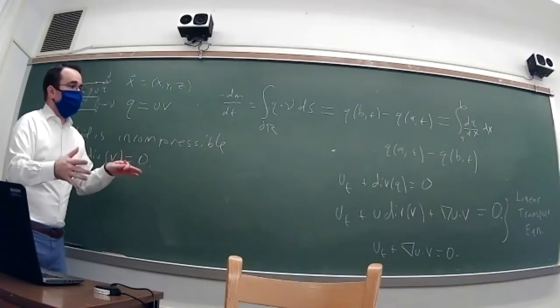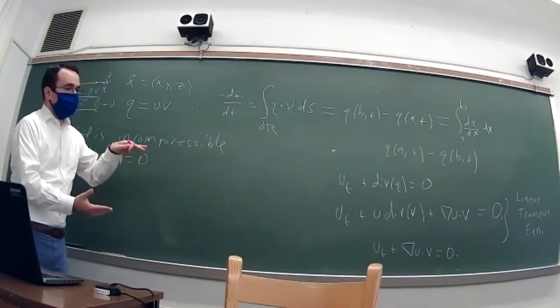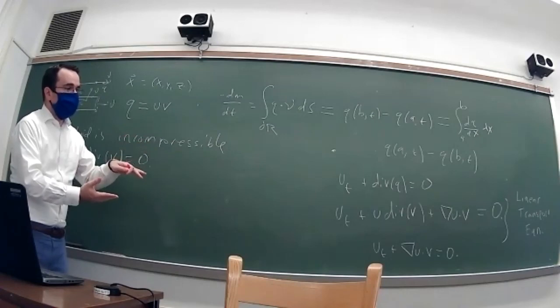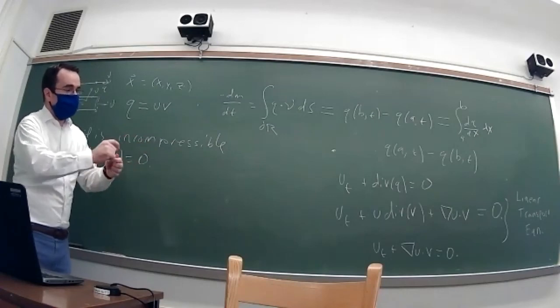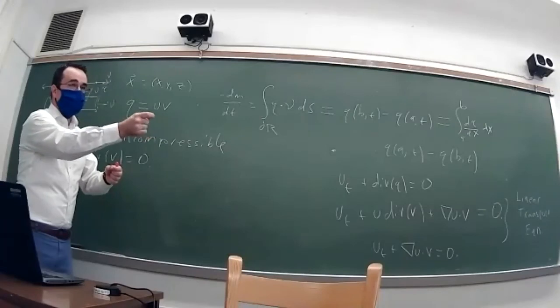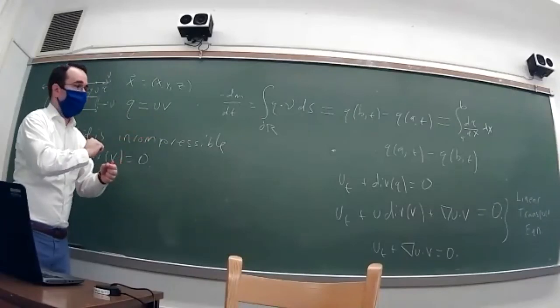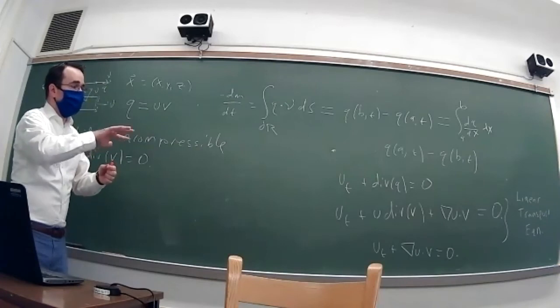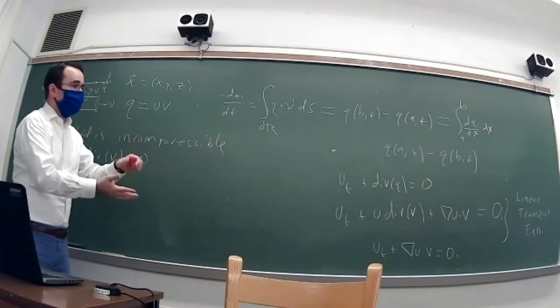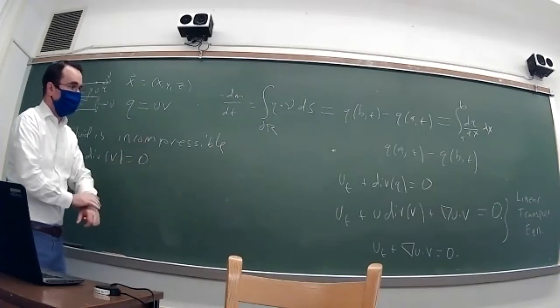So it doesn't even say that the fluid can't be compressed. It says that if you compress the fluid in a way that's not related to heat, then along the characteristic lines, that's where the mass is guaranteed to not change. So it's not even uniformly saying that the concentration won't change as you expand or contract it.